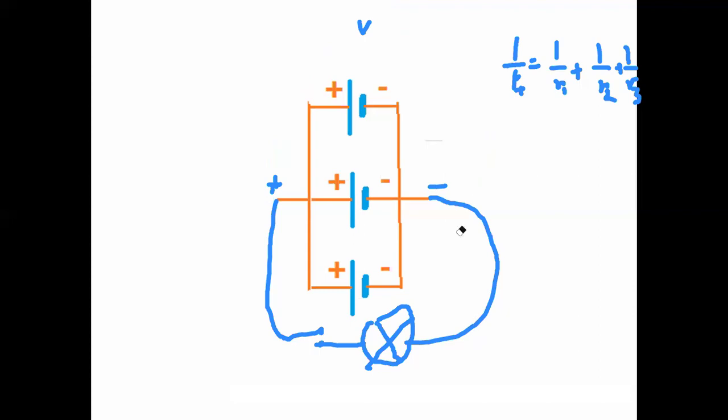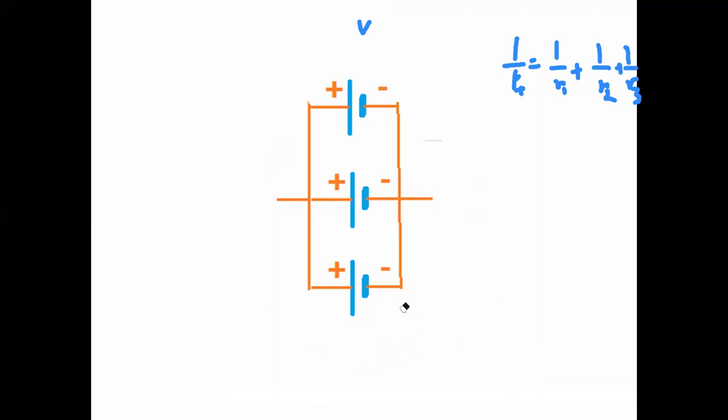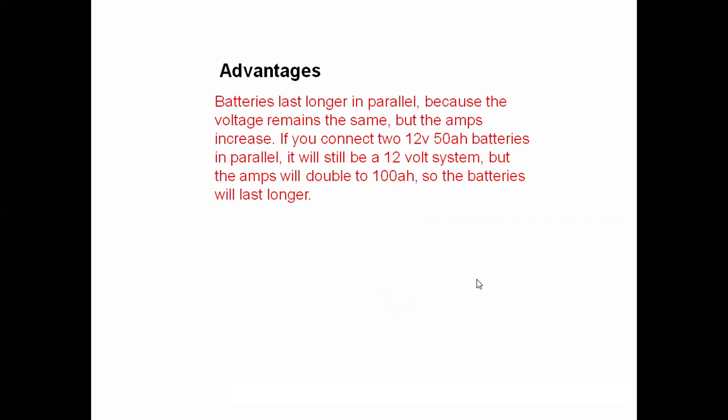So that depends upon the requirement. Sometimes when we need more EMF, then of course we need to connect them in series to acquire greater total voltage. But what is the advantage if the EMF is not increasing? That is, the total resistance decreases, and moreover, the cells work for a longer time. Okay, they last longer in parallel. They continue providing energy for a longer time.